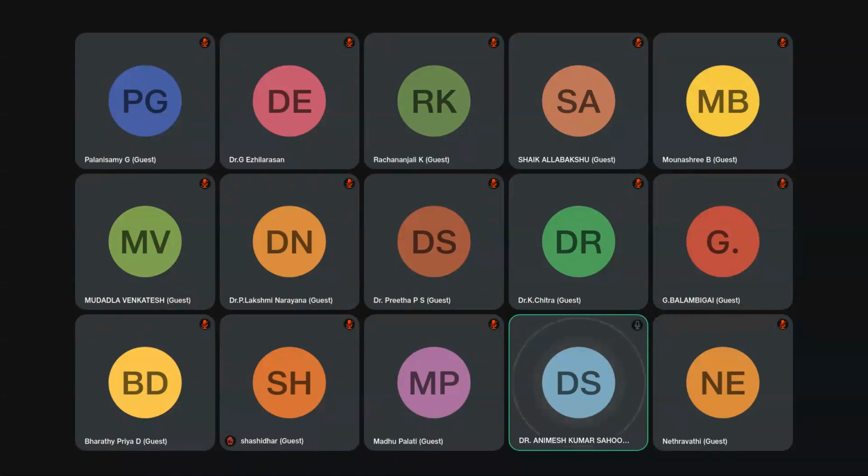And with that controller, you can actually interface a physical inverter to an actual grid. They also provide their own GUI software, like RT-LAB for OPAL-RT. There is something similar called RTDS, which uses RSCAD simulation software to put the controller in real time. So OPAL-RT and RTDS are the two trending real-time simulators, and also the company names are the same. Those are the platforms you can use.